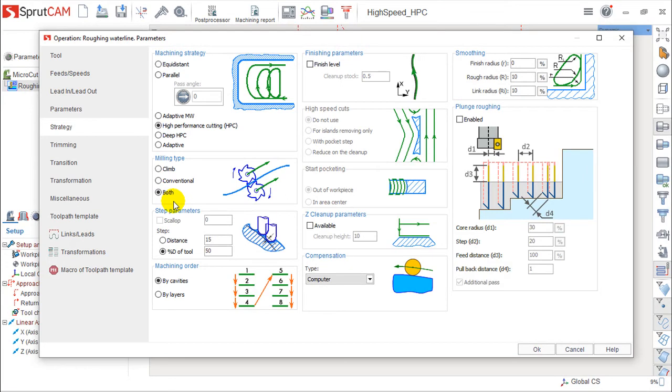So this will influence also the quantity of movements and the quantity of lift ups we have in the part, so it's a very important parameter to consider. But in this type of toolpath, we have this type of movement, which we can call the trochoidal movement, which is smooth, but it takes longer in terms of milling time on the machine.